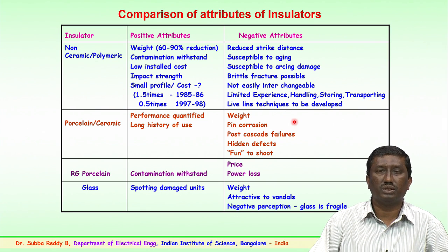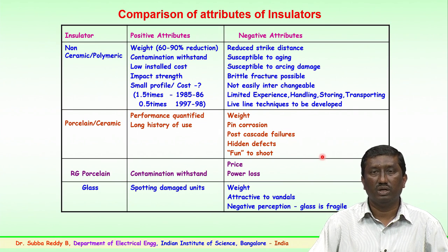So, a lot of issues which are cropping up have to be addressed, whereas porcelain or ceramic performance has been quantified with a long history of use of more than 100 years. But yes, there are negative attributes: the weight of the string goes on increasing with the voltage level, pin corrosion has been observed, sometimes cascade failures have happened, and hidden defects of the material could lead to a problem.